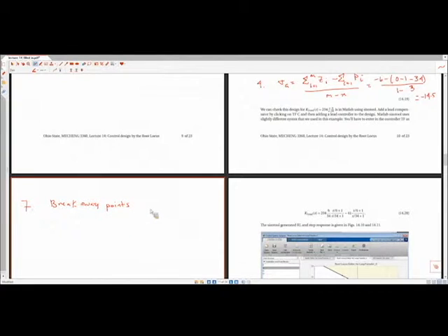Okay, remember the formula for this, we look at what's the numerator. The numerator here is n of s equals s plus 6. This is what we designed it to be. The denominator is going to be equal to s plus 1. These are the poles coming from the plant, but we also added a pole from our controller, s plus 34. If I were to multiply this out, this would be s to the third plus 35s squared plus 34s would be d of s.